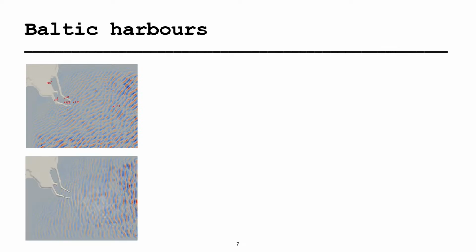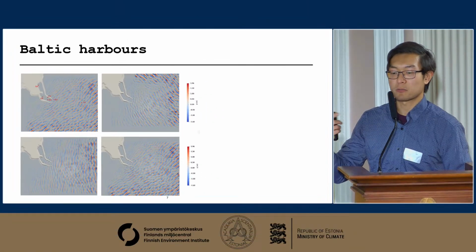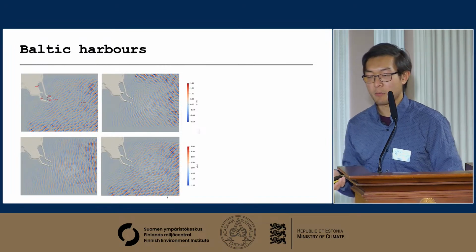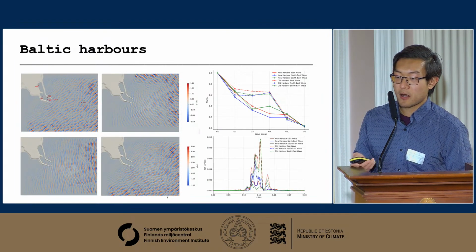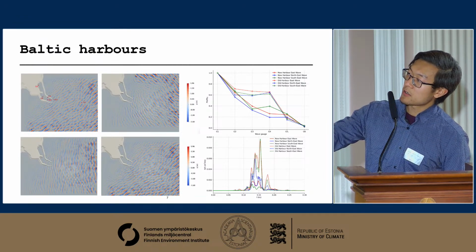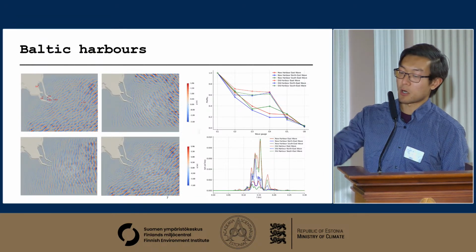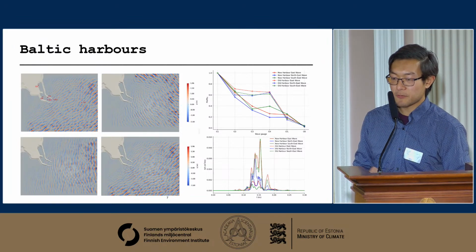With the flexibility of a numerical wave model, we can look at wave propagation from different directions to investigate what could possibly be the most dangerous scenarios for the harbor, for example. And then we can also compare the new harbor layout on the right-hand side of the images. All of those are with the new harbor layout, and the previous slide is the old harbor layout.